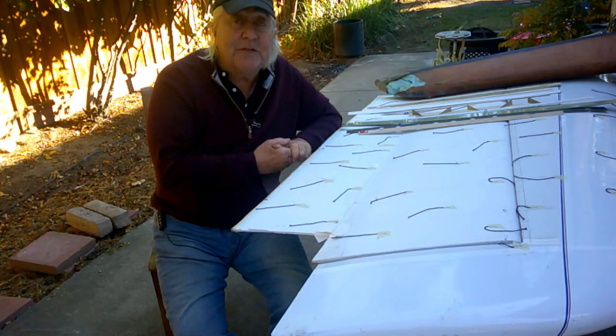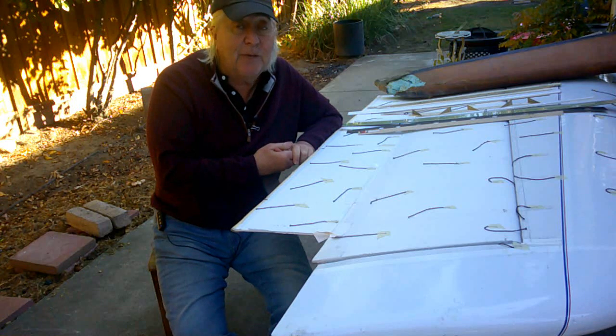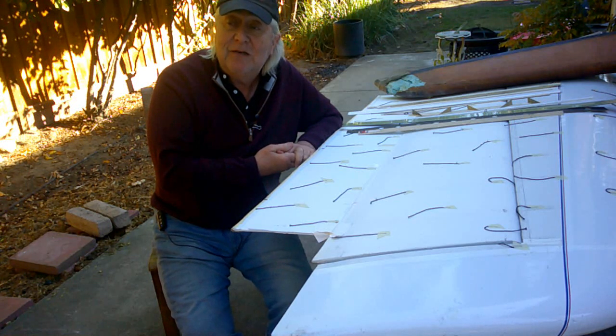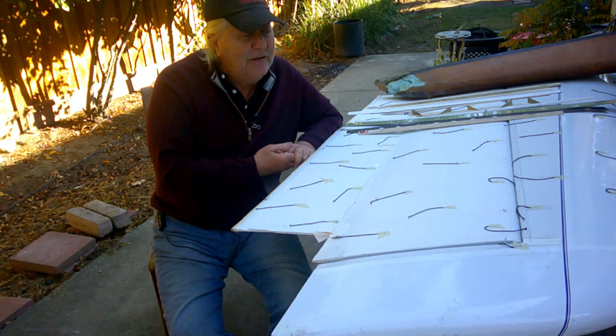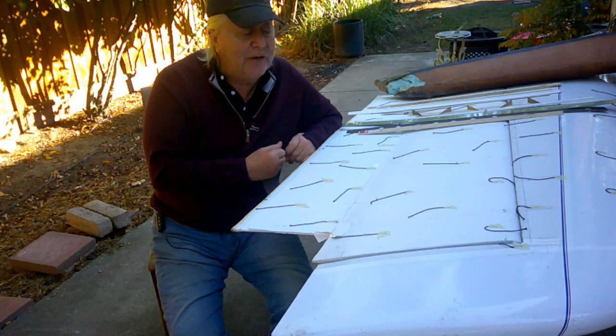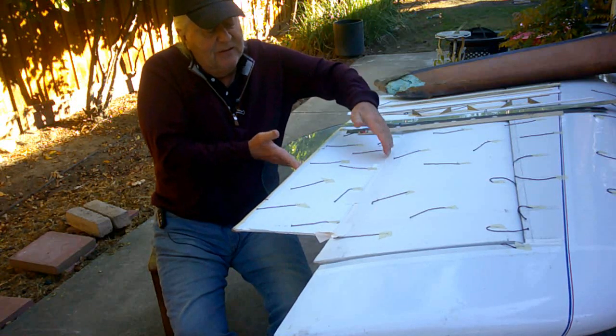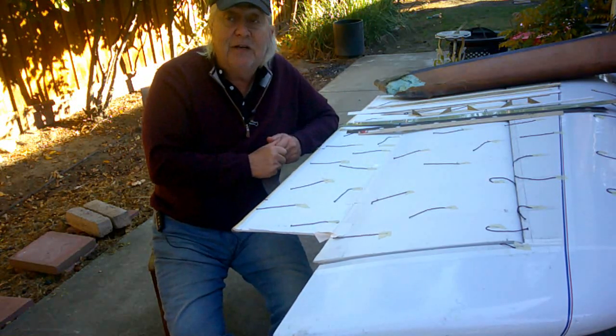Well, these control surfaces are much larger, and they're not doing the job because the flow's separating. And I went around and around and around about that. It's like, what the heck changed? Well, I had long strip elevons on my original wing. They were about 6 inches wide. They were about this size, maybe 8 inches wide. And they were stuck on the trailing edge.